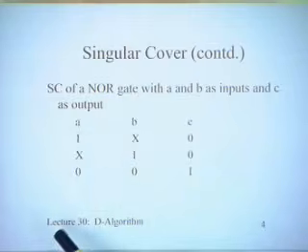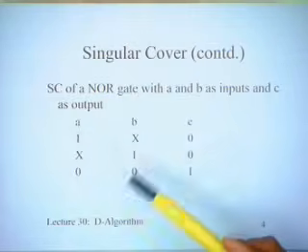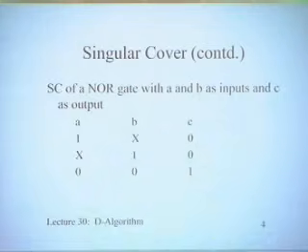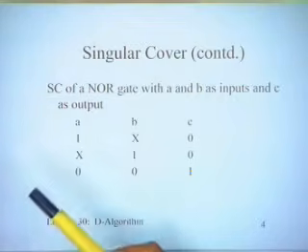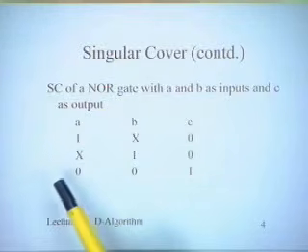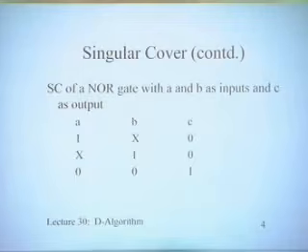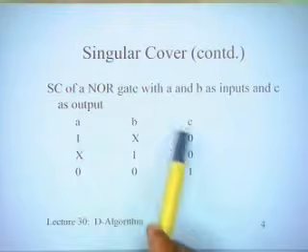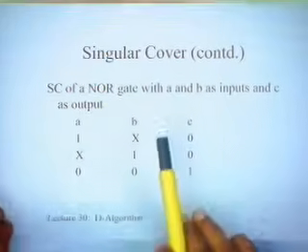These gates are symmetrical around inputs, but if you consider combinational logic which is more complex, it's not necessary that they are symmetrical. For example, I can do the singular cover for a multiplexer. There are three inputs, A input, B input and a select input. Around A and B the function is symmetrical, though that's also not fully symmetrical because you have 0 and 1, selecting one with 0 and another with 1. As far as the select input is concerned, it's completely asymmetrical around it. So you start from a truth table and then generate the singular cover, and that is one of the starting points.